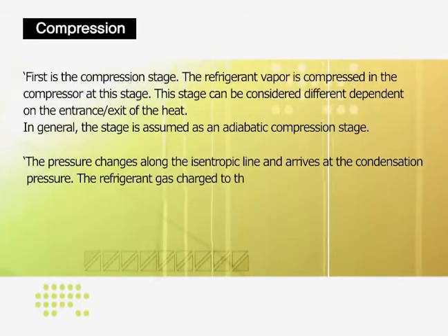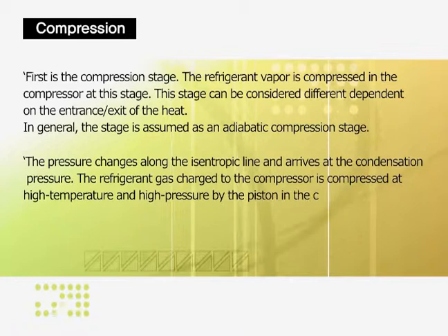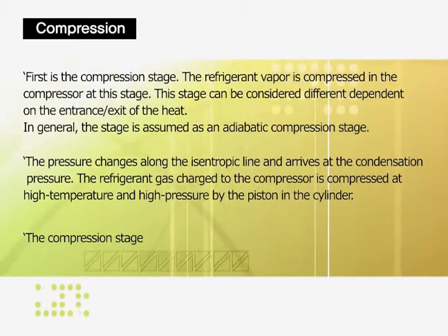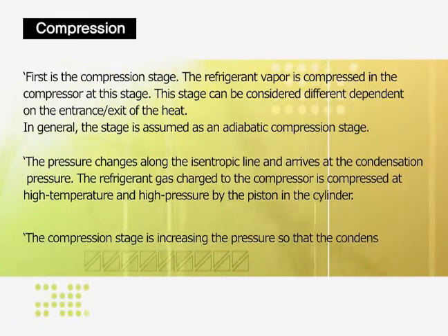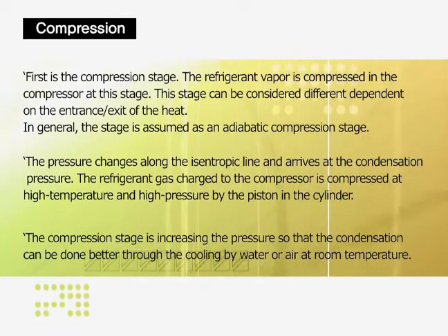The refrigerant gas charged to the compressor is compressed at high temperature and high pressure by the piston in the cylinder. The compression stage is increasing the pressure so that the condensation can be done better through the cooling by water or air at room temperature.